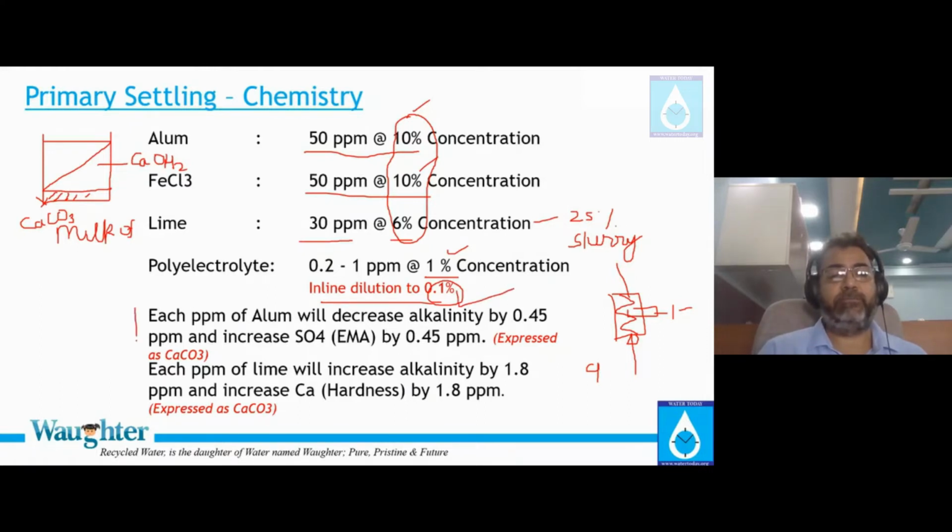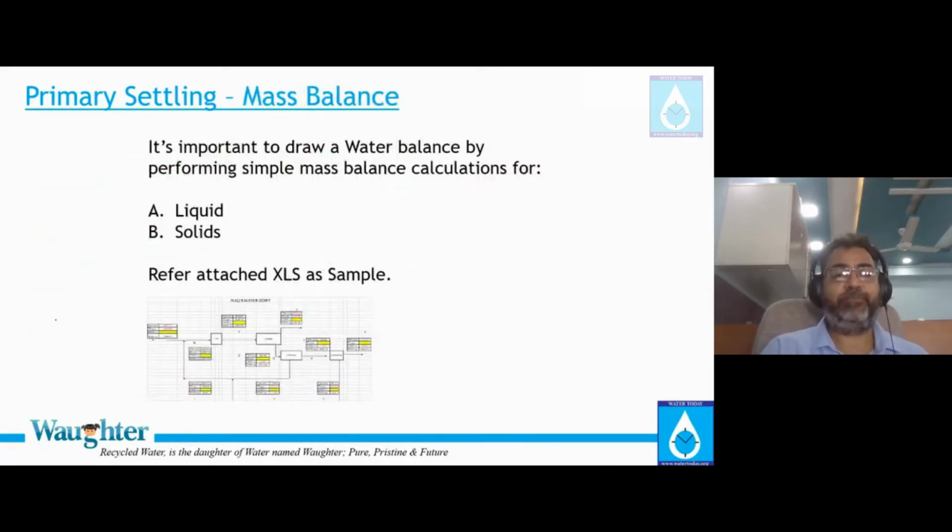And these two are, of course, applicable if your water is being used for this. Typically in wastewater treatment, we do not do alum, ferric chloride, lime, and poly treatment. We just do only poly treatment. But sometimes you may have to do alum, ferric chloride, and lime treatment in ETP if the effluent is mixed with the sewage, and especially in the tertiary area, not the primary or the secondary area. In the secondary area, we don't use any chemical, but in the tertiary area, you may have to use chemicals.